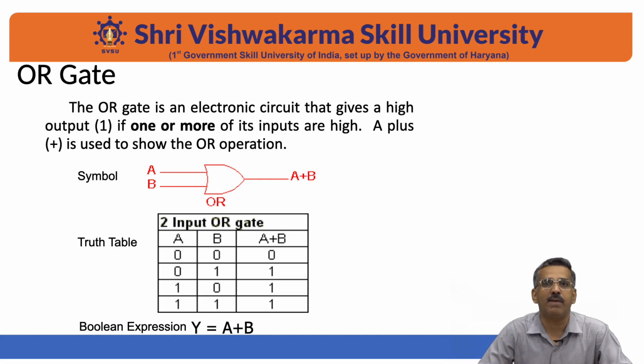In this circuit, we have applied two inputs, that is VA and VB. So the number of situations, the number of conditions, will be equal to 2 raised to power 2, that is 4. Under this condition, we are looking that this circuitry is an OR gate, which is the electronic circuit that gives high voltage whenever one input is high or more than one is high. In this condition, we have the logic of the OR gate, which is fulfilled by this circuit.